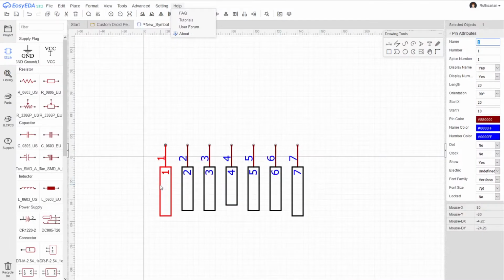So, for example, I know that what here is listed as pin 1, I know that's ground, so I'm going to call that ground. And pin 7, I know that is V. Do I want to call it VDD? Sure, why not? And then what do we have here? The second pin connects to pin 5 on the chip, which is the serial input pin. Gold finger 3 is connected to pin 2, which is the serial output.